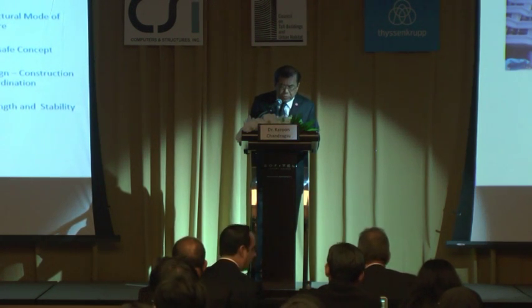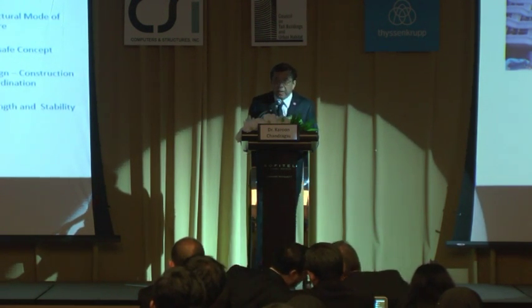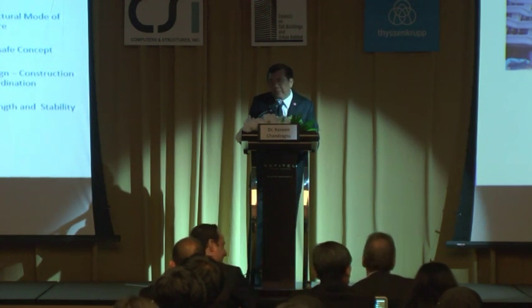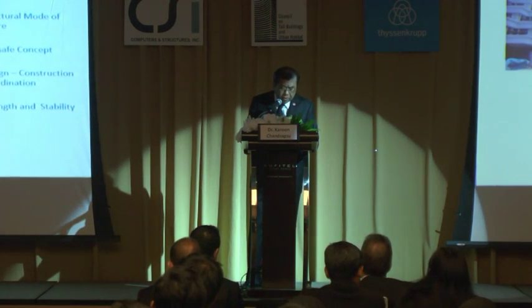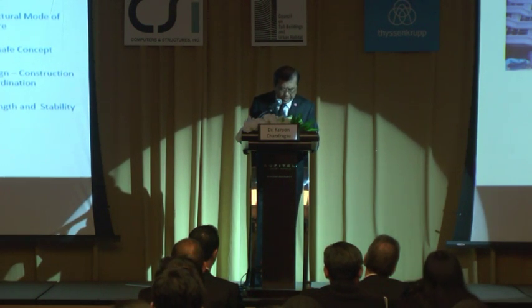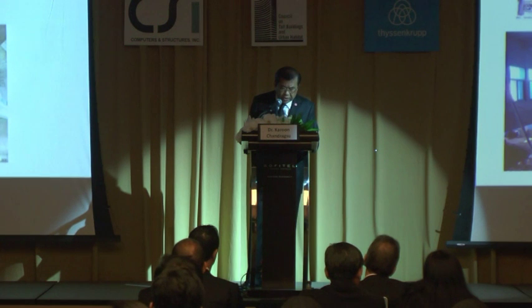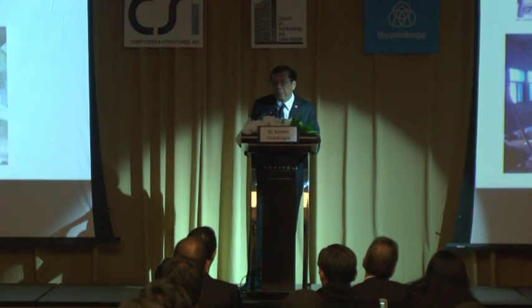It is elevated to 30 meters above ground and supported by two mega columns and one rectangular service core. This building required extensive and advanced precision of structural analysis to ensure stability. Certainly, construction technique dominated the design. The building contains column-free spaces with several long-span structures to accommodate an auditorium and atrium hall inside.